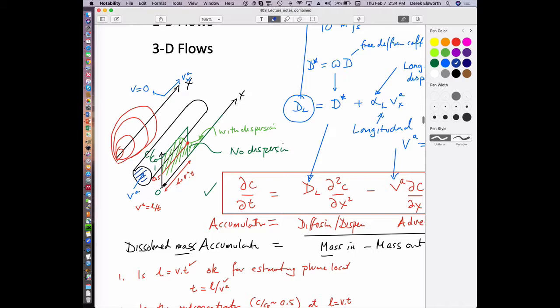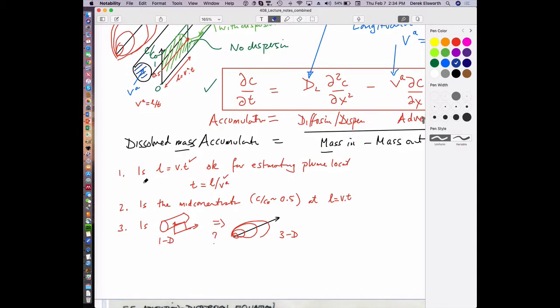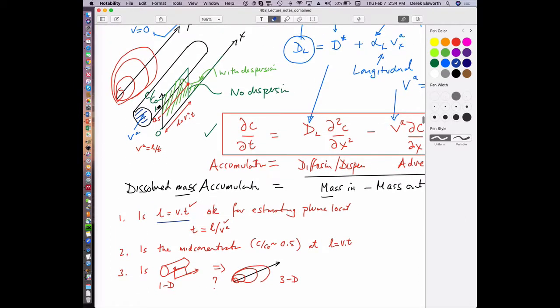And we know that diffusion is going to carry it at some velocity, not a very fast velocity maybe, a velocity that's independent of the velocity of the water, and we know that due to diffusion it would exist along here. And so we could have probably guessed that our answer to each of these questions, whether this is a good approximation of where the mean concentration would be, can't be true, because for a diffusion only case it will always predict that the mean concentration would be at 0 length along here. Hasn't traveled at all, and that's not true.